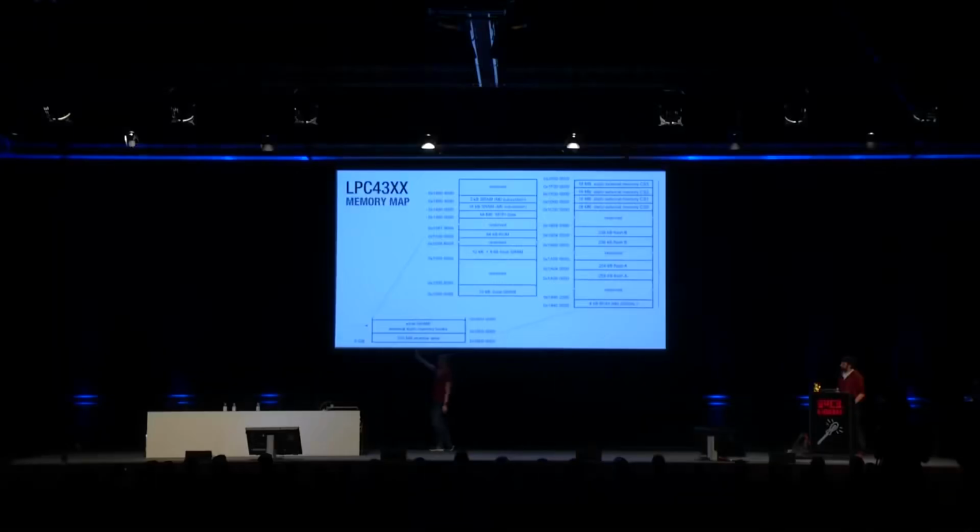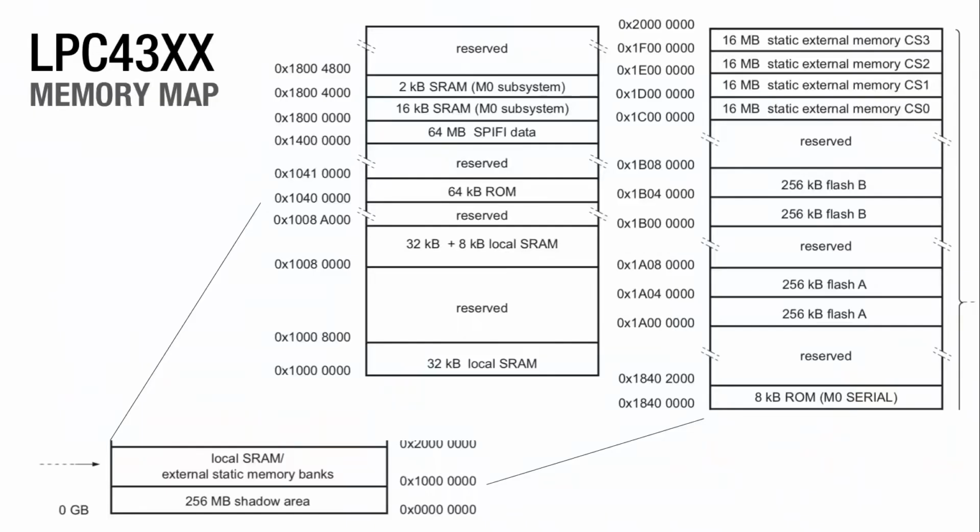You might be saying, well, why is it interesting to attack this ROM? One is that on a bunch of these devices, it runs from this shadow area at the start of RAM, because the Cortex-M microcontroller wants its vector table located at address 0. So it's very low in RAM. Everything that's interesting follows it, including on-device parts with flash, the contents of flash over here.